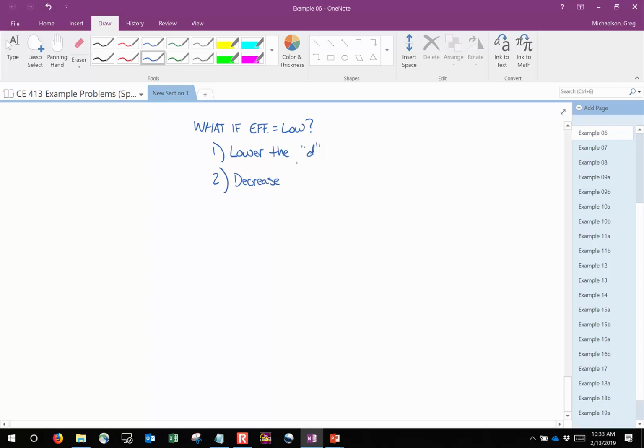Well, okay. That's a great question. The 0.98 square inches is just an absolute minimum requirement that every beam has to withstand. But that is independent of the moments that we're actually placing on it. In other words, if I lowered the load on this beam, that limit would still be there. But we could just decrease AS a bit.